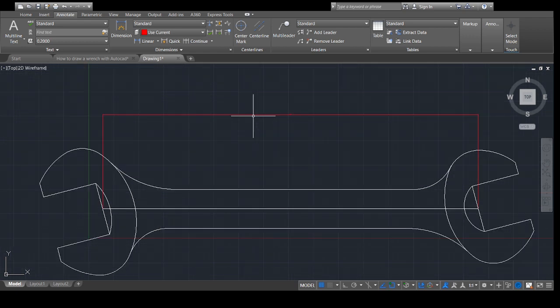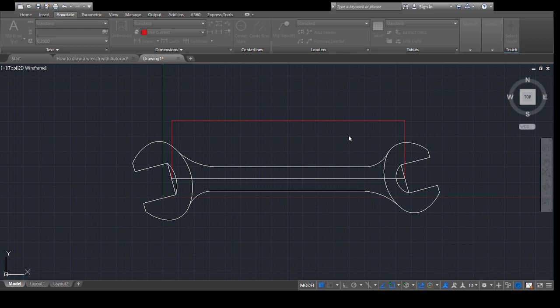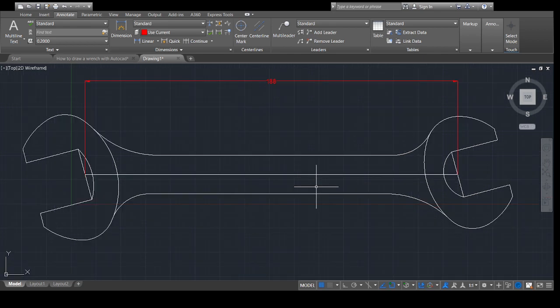So you can see the text are not visible. So I'm going to click there, down there, then modify. I'm going to change the arrow size and the text size. You can have it as 2.18. Now have the text also, text height being 2.18, and then primary unit decimal, no decimals. Right. Now you can see it's visible.